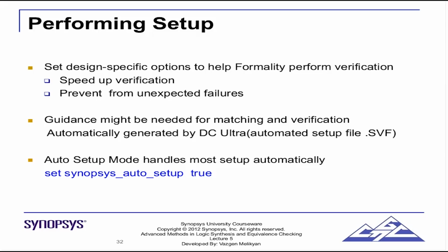Now you can take care of this in the setup. In the setup you can say that I have clock gating in my design, so please make sure that all such cases of clock gating are verified properly. There is one variable which controls that. So this is part of setup. The best thing you can do is use Synopsys Auto Setup to prove. This will read the SVF and the synthesis options and prepare the setup for you. This is the quickest thing you could do.